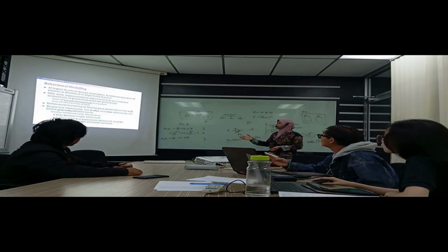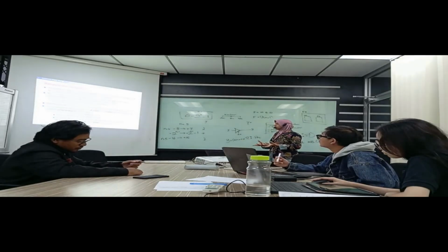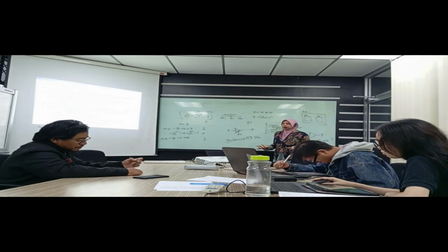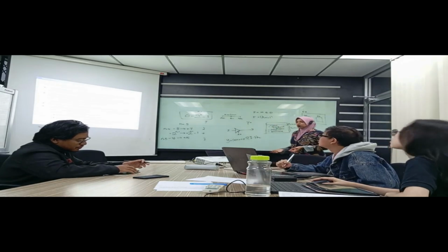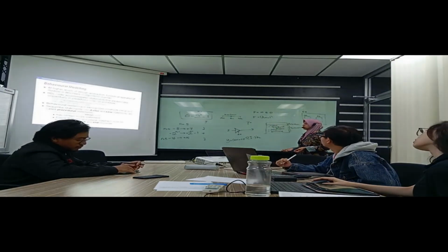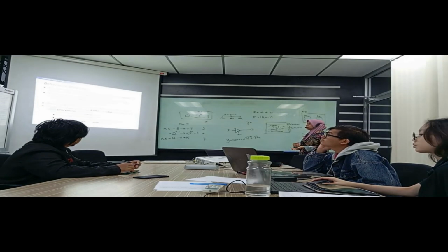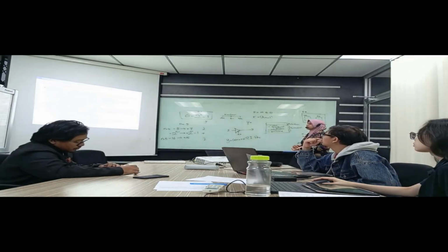In Verilog, we use constructs similar to C. So you can see the writing of the code is like that. We use constructs like if-else and case statements. This we call the procedural statement, and you need to write it in the always block. A block may contain a single statement or more than one statement.